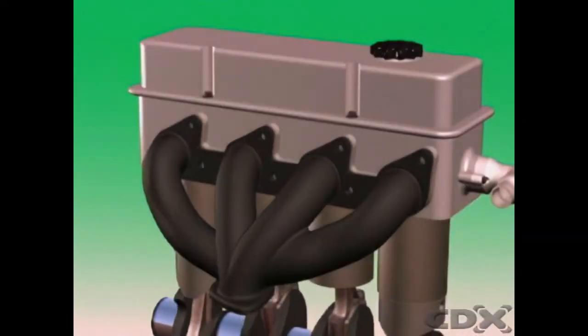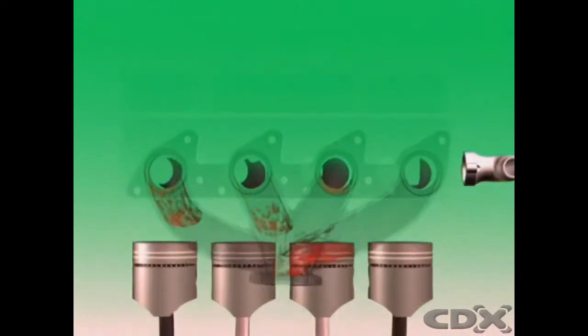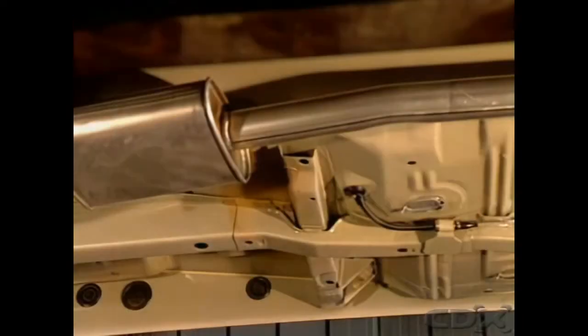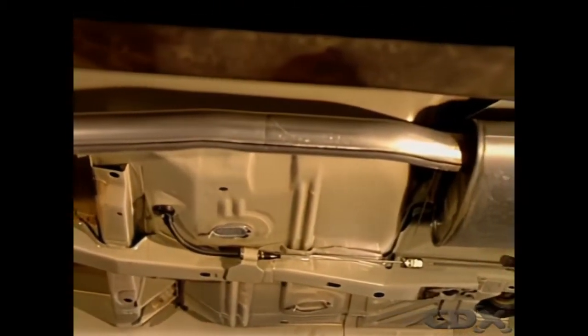During engine operation, each time the exhaust valve opens, pulses of hot exhaust gases are forced into the exhaust manifold. These hot, rapidly expanding gases produce a lot of noise, some of it at very high frequency. The exhaust system does several jobs. It has to reduce the noise of the exhausting gases to acceptable levels. It has to discharge the gases safely, far enough away to prevent them re-entering the vehicle. Some of these gases are highly poisonous.